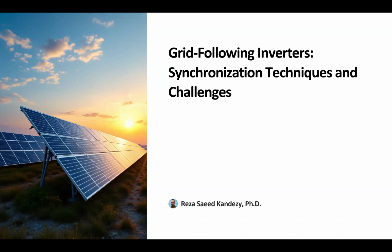So far, let's summarize what we did through the semester. We've gone through the concept of the inverter. We learned about the topology. We learned about the PWM and how we could control the switches in our topology, each one of them, either like a half bridge, full bridge, or even cascading multi-level inverter.